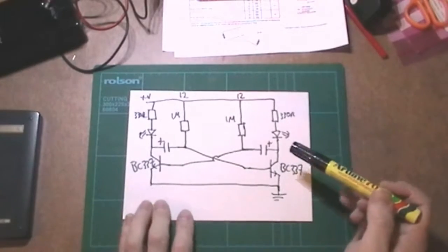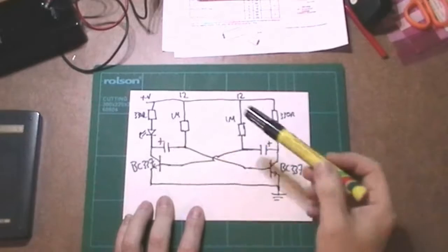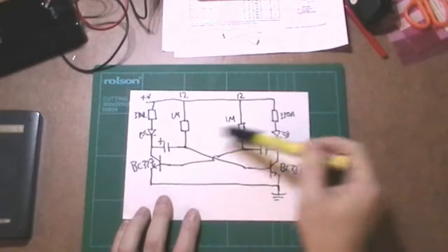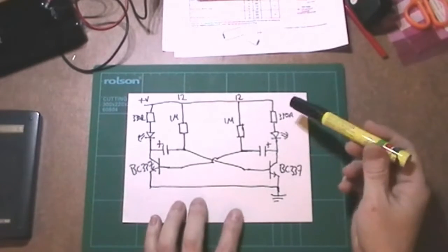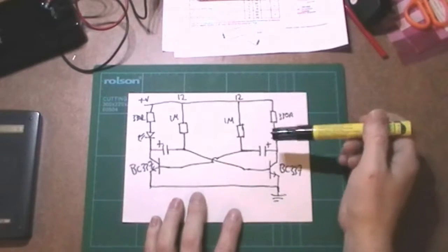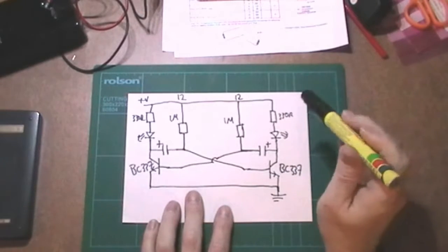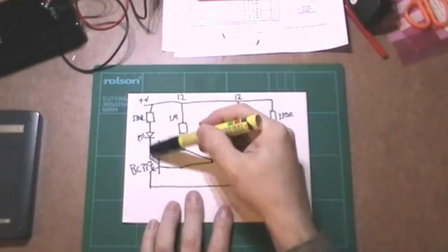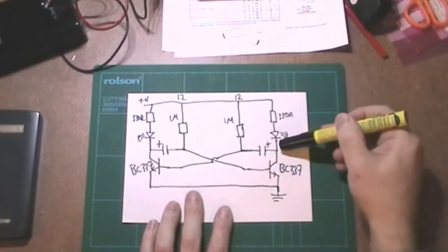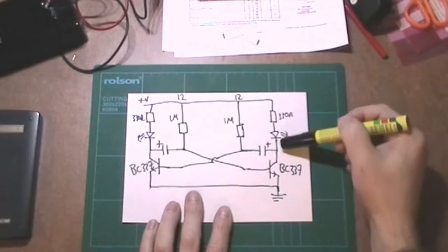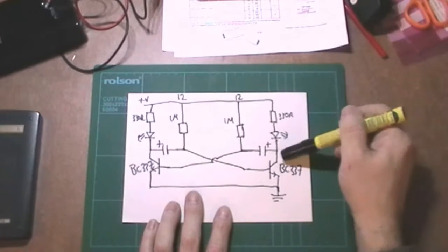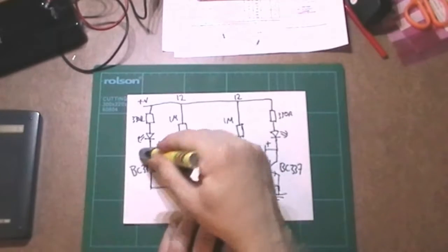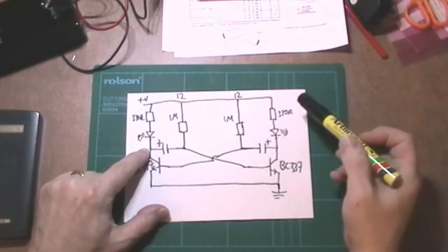Okay, so here we have my circuit, very crudely drawn. A couple of transistors, a couple of capacitors, some resistors, LEDs, so I can see that it's actually flip-flopping between the two states, turning these two transistors on and off. Now, the way I see it is that these are only here so I can see that it's actually operating. So this point is at effectively supply voltage, 12 volts. So what am I saying there? That is going to be at 12 volts when it's turned on. So is that point there going to be at 12 volts?